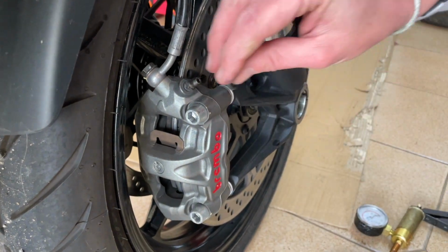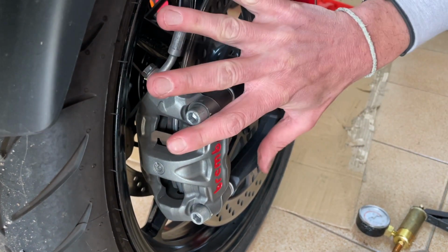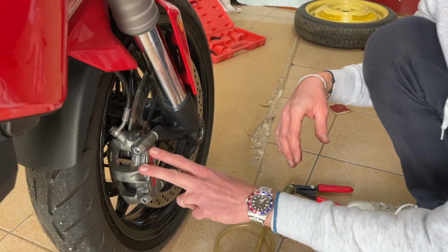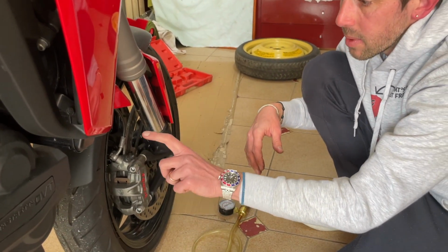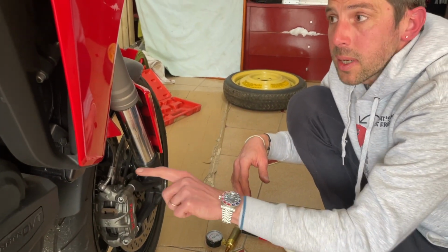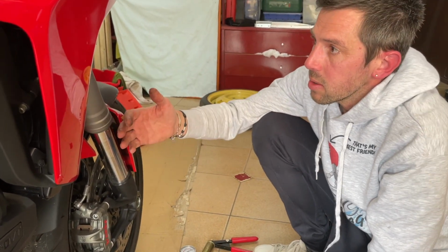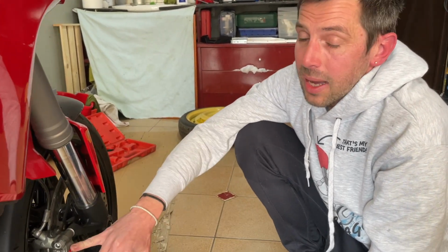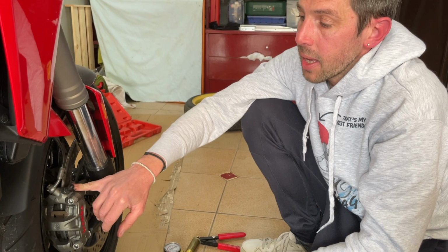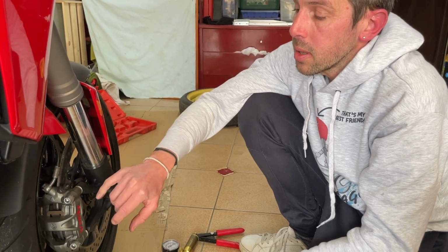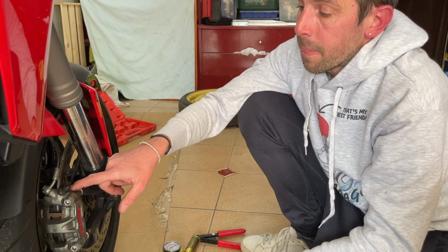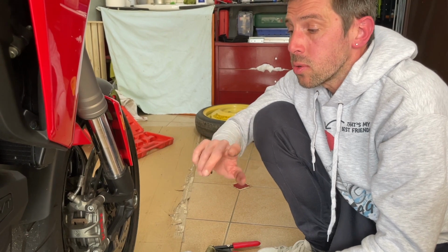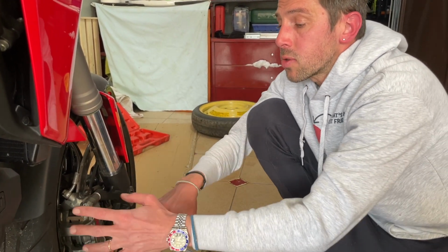As you see, there are many differences in the braking system, especially on the front line, depending on the bike. Most of these bikes have two calipers, one per side, and each of them has its bleeding valve. How they are connected could change. In principle, you should bleed first the last caliper, so the one that has the longer hose, and then the second one. To do a perfect bleeding of the system, the best way is to remove the caliper.